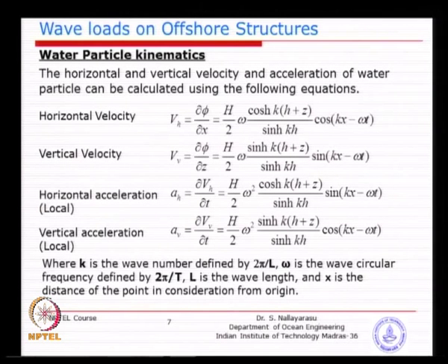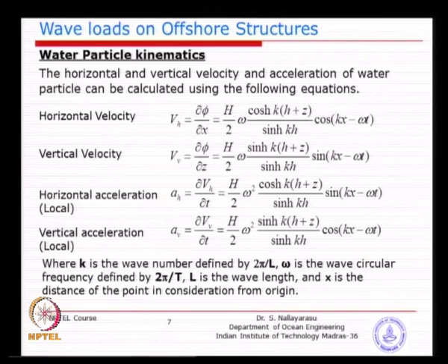The horizontal velocity is del phi by del x, the vertical velocity is del phi by del z, and then the horizontal acceleration and vertical acceleration follow from the associated velocity differentiated with respect to time. It is a very simple idea, and as long as you know these equations, all of these terms will be known to you, for example, wave height and wave frequency.